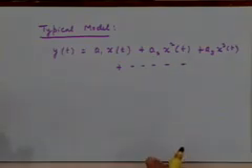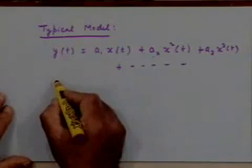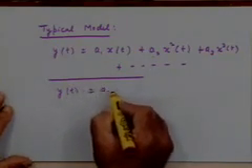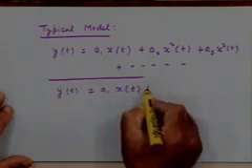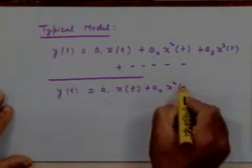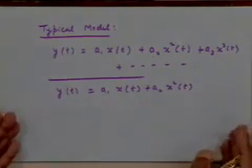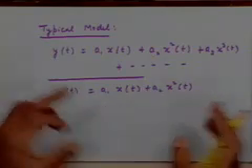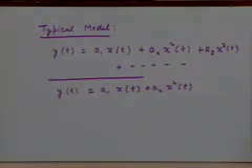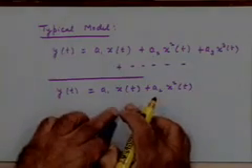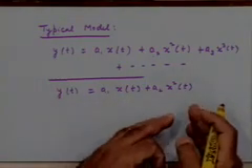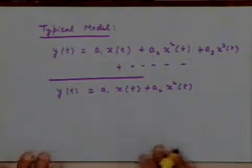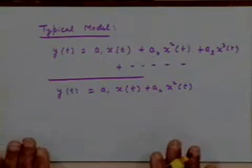Now suppose that is the case. Suppose we take a very simple nonlinearity of the kind a1 x t plus a2 x square t. One thing is clear, that the output is not a replica of x t, and therefore there is a distortion, because we would like the output to be simply proportional to x t, but we have additional components like x square, x cube, and so on and so forth, right. So therefore there is a kind of distortion here.